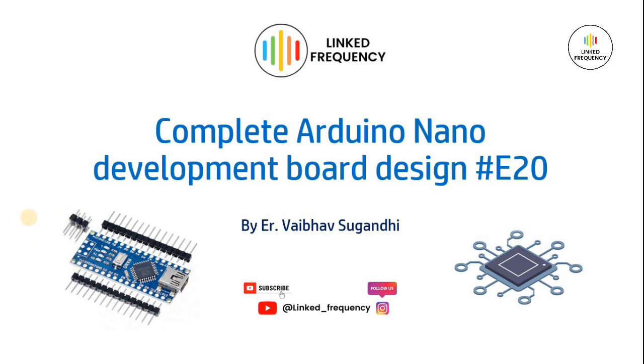One is not adding these SPI connectors. You can see here, these SPI connectors, a 6-pin header, are necessary for connecting SPI protocol based peripherals directly to the board without using these normal GPIOs. In fact, internally these normal GPIOs are only connected to these SPIs. They are not separate or special things. They are just a utilization of these SPIs in a direct fashion. However, we have not added that because we felt it is not necessary for us at this point of time.